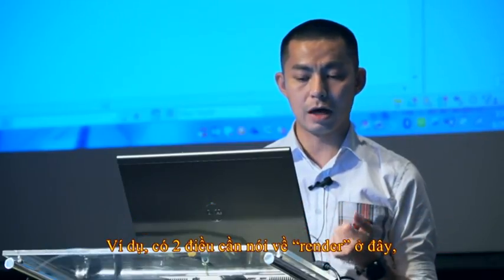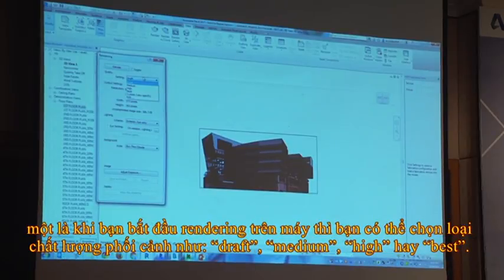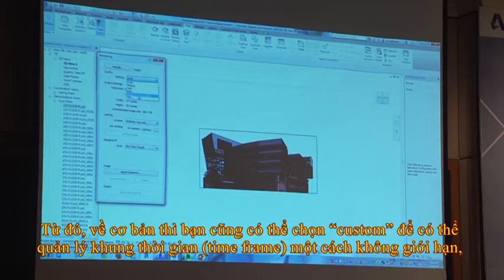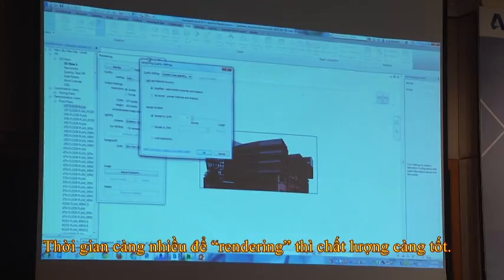Okay. For example, there are two enhancements about rendering over here. One thing is that when you start to do a rendering, previously you could only select the type of rendering as draft, medium, fine, and best. Okay, so from here basically you can start to choose what we call custom. This custom means that I can do a rendering with an unlimited time frame. It means that I can let my computer run for a few days, and the more time the rendering takes, the more detail and the better quality your rendering is going to be.